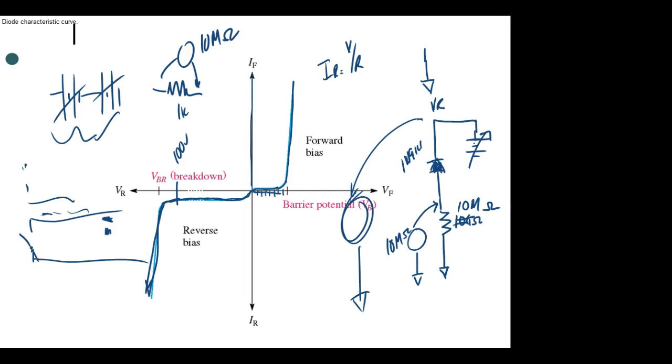But this is something we take for granted in DC and AC and stuff like that: that the meter has no effect on the circuit. But that is not true. You're putting a resistor in parallel with something. As long as it's a very low resistance, your meter has no effect. When we get up to this 10 mega ohm resistor, if this has 10 mega ohms and that has 10 mega ohms, then we're going to calculate our current at what? We're going to calculate our current at 5 mega ohms, because half the current's coming through the meter and half the current's going through that resistor, right?